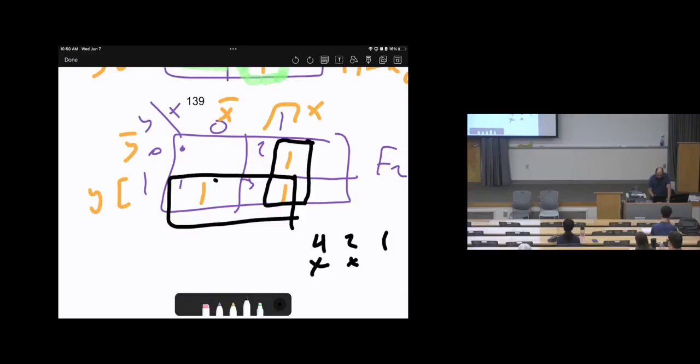Look at the first group; I'm going to make it number 1, and this one number 2. Look at box number 1. It's located at x, then the other side at y bar and y. Is that right? It looks like x times y plus y bar. Y plus y bar is 1. It will be x times 1. So it will be x.